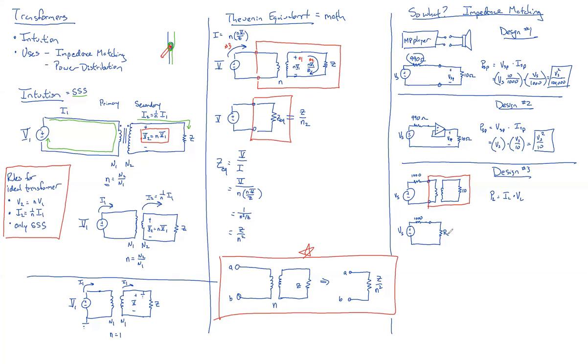So if we make this resistance 0, it's bad. If we make it infinite, it's bad. There's got to be something in between where it's optimal. Do you remember what it is? You worked it out in circuits 1, and we talked about it in circuits 2 briefly. In general, if this was a Z, when your load impedance is equal to the complex conjugate of your source impedance, that's where you've got the greatest power transfer.